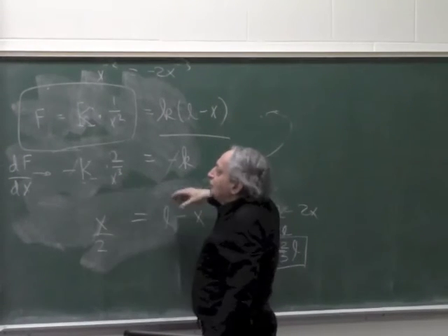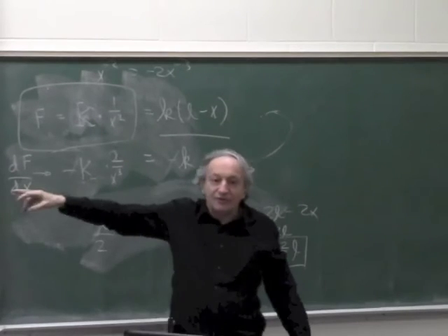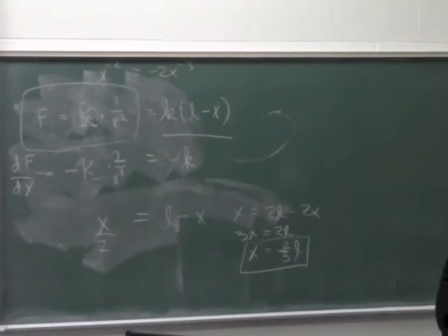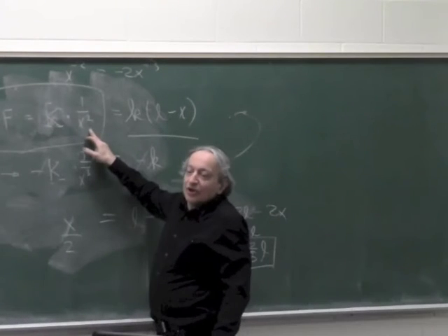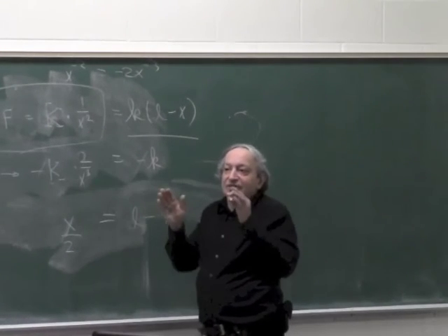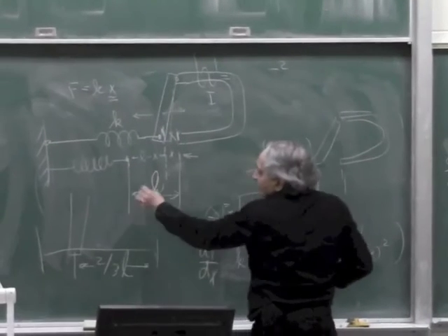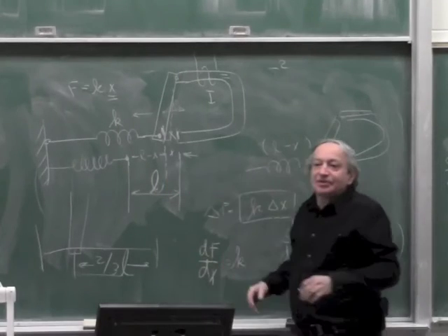So this derivation is not a function of K, and it is valid also for electrostatic actuators. So bottom line, for any actuator which is inverse square law, you can only use 1/3 of the travel, because for the first third it seems to work, and once x is 2/3, it snaps.